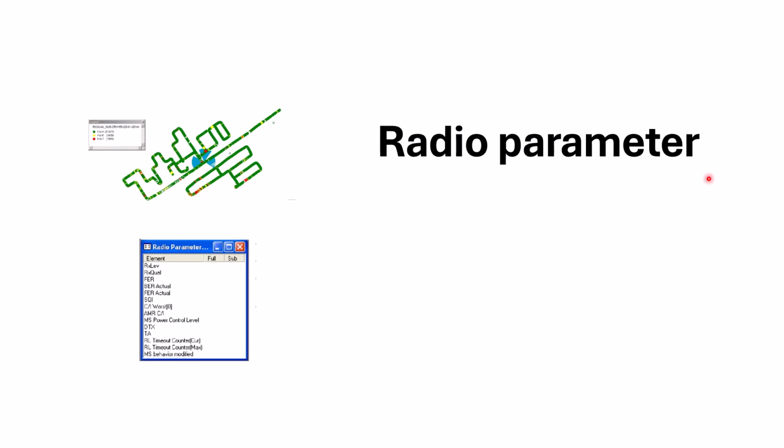Use the measurement for voice quality. Important threshold for calls without frequency hopping should be less than 4. For calls with frequency hopping should be less than 5. Value 0 to 3 is generally acceptable, good. Value between 4 to 7 indicates degraded service quality. You can see in the pictures, you can analyze.